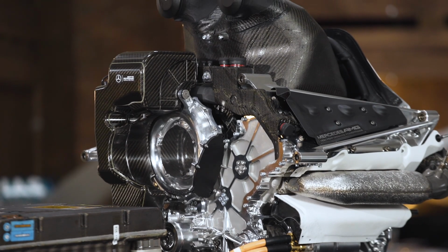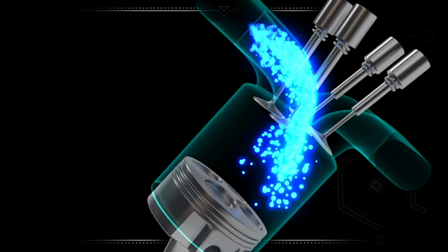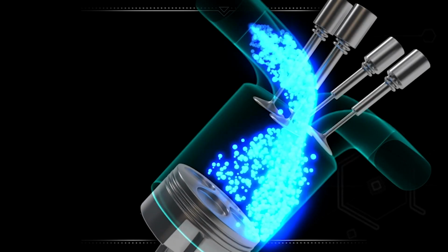What's happening there is the pressure inside the cylinder is slightly reduced as the piston moves down, and the air in the plenums, prepared air ready for combustion, then rushes in because of the pressure difference between the cylinder and itself. Also during that stroke, as it's a GDI engine, the fuel gets injected directly into the cylinder. So what we end up with at the bottom of that stroke is a nice air-fuel mixture. We close the inlet valves and we compress it. So that's the second stroke, compression, squeeze.